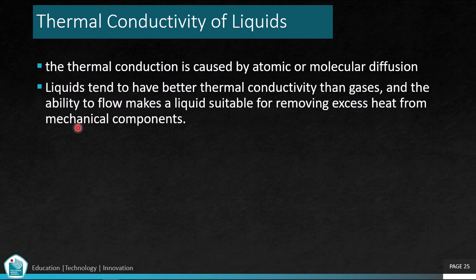Liquids tend to have better thermal conductivity than gases, and the ability to flow makes a liquid suitable for removing excess heat from mechanical components. The heat can be removed by channeling the liquid through a heat exchanger.